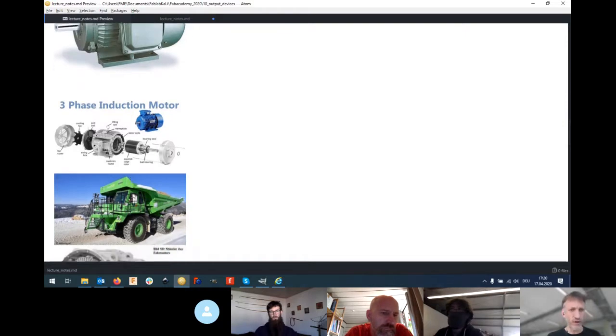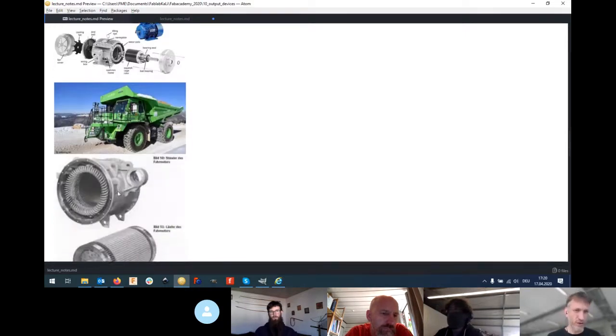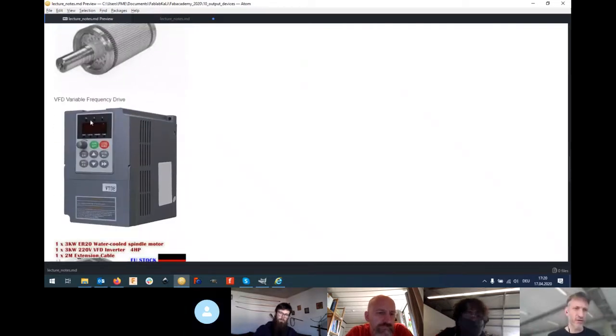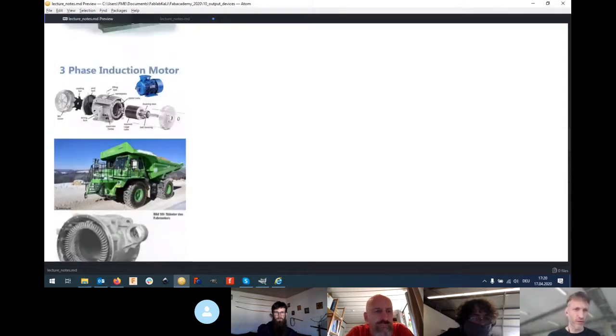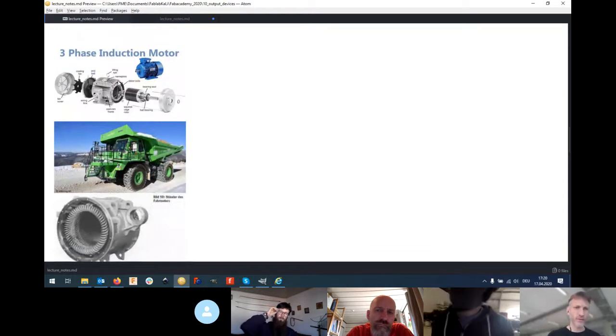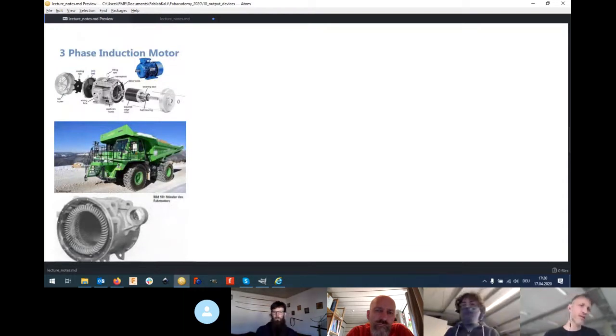Yeah, those are used anywhere from big trucks to, this is the one from the ICE or from the S-Bahn. It's the most produced motor in the world, and in order to adjust its speed you use what is called a variable frequency drive, which is a little box that generates a custom frequency. If you run one of those on regular AC, it runs at a constant speed because you have the 50 hertz and the 3 phases, and this is how most of them run.